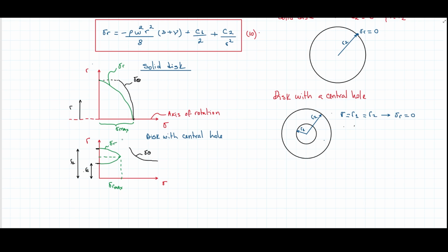And in this case, actually in both cases, we could say that we keep the same order of magnitude as in the case of thick shells, where the circumferential stress was always larger than the radial stress. Awesome. Now, we need to come back and see one specific application.